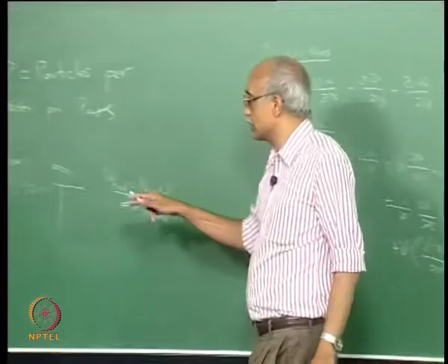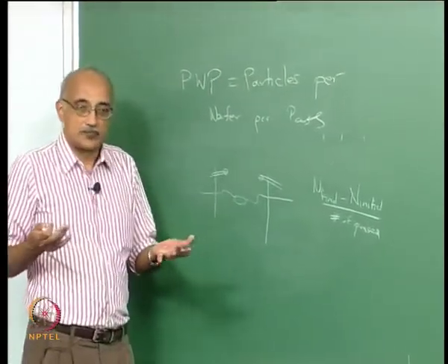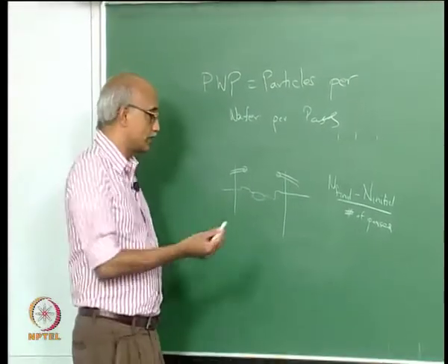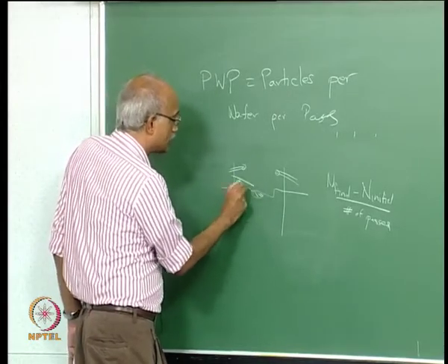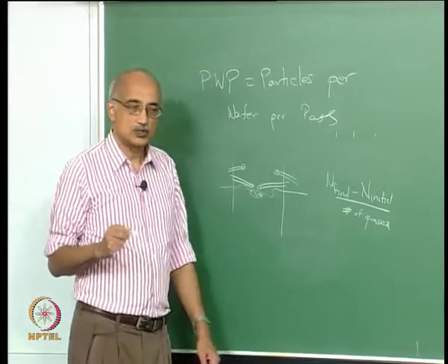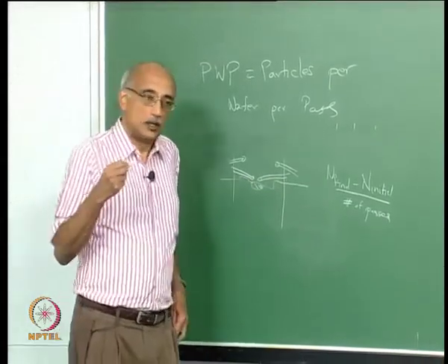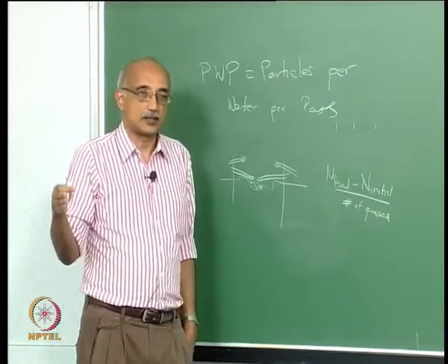Here what we are talking about is locating these particle counters right where the process is being done, inside the process tool. For example, if I am putting down some patterns on this wafer inside this tool, you actually stick this particle counter as close to that operation as possible, so that you actually measure how many particles are being generated by the process of putting this pattern on the wafer.